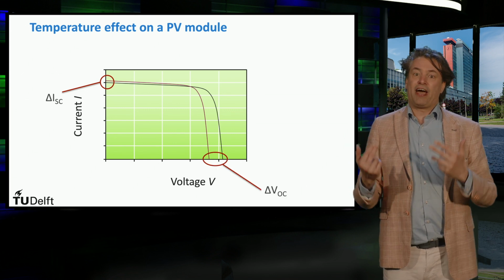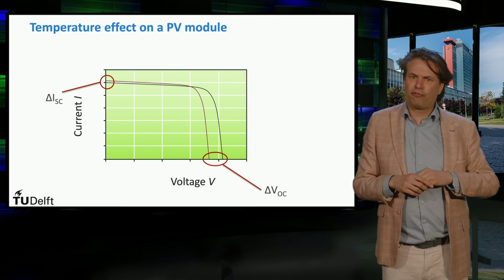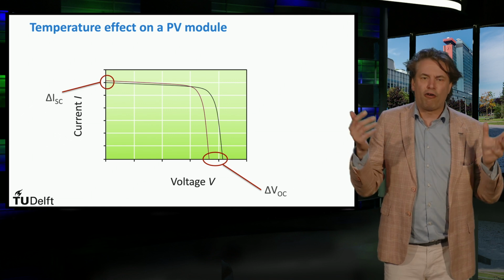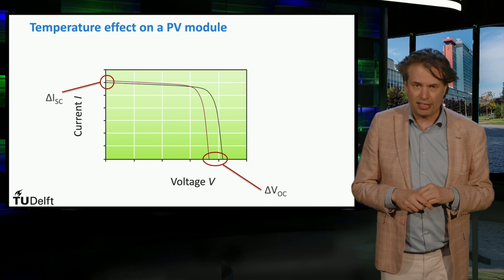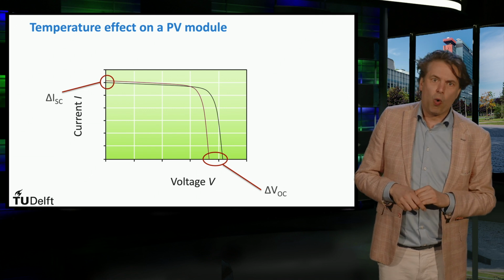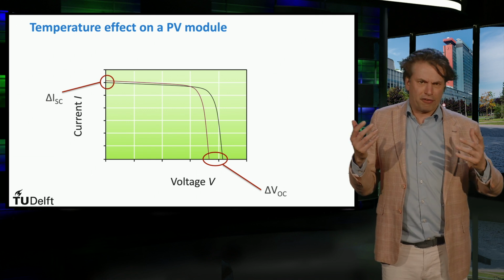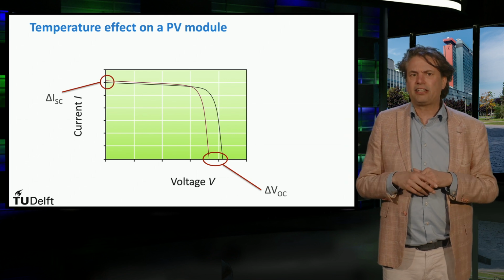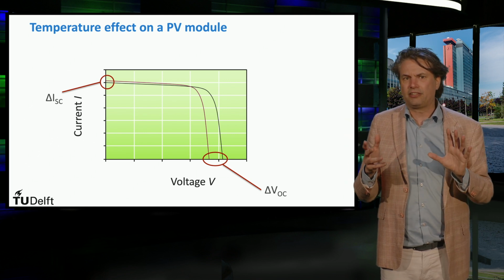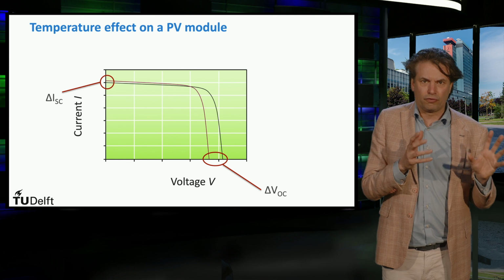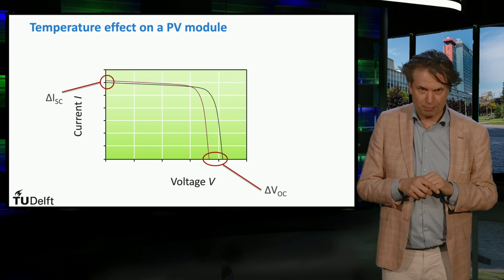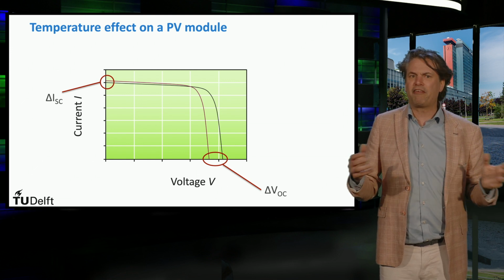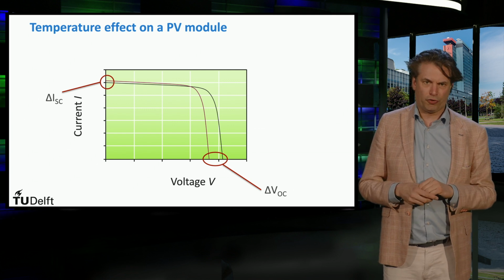The decreasing effect on voltage can be explained from this form of basic diode equation seen in the earlier weeks. While the temperature affects the various terms in this equation, the net effect of the temperature is that the VOC decreases linearly. The magnitude of reduction varies inversely with the open circuit voltage.